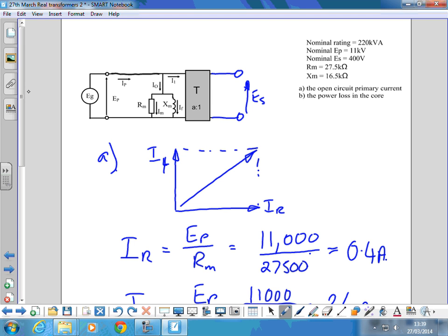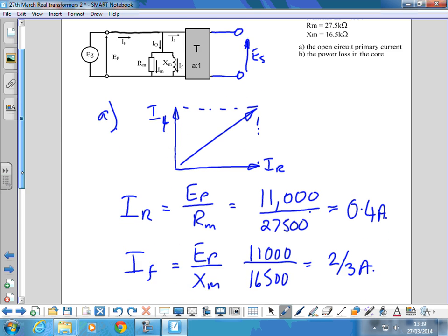All the heat comes from the resistance. So we want the current IR. We can use the current IR and the voltage, or IR squared times its resistance, or V squared over R. Any of them will do.